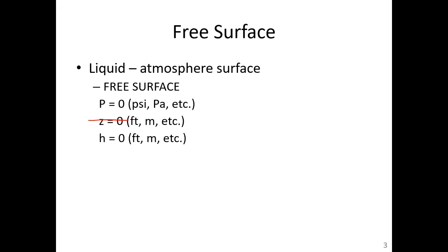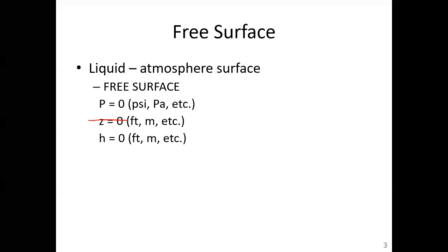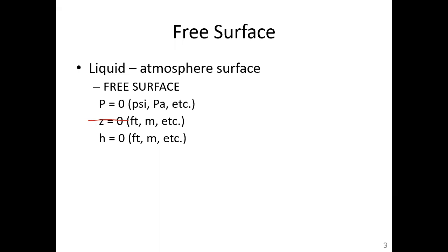When your atmospheric pressure is non-zero, you're typically using the absolute pressure measurement data. And you can certainly do problems in one or the other, but you can't mix and match. To get from an absolute pressure to a gauge pressure, we have to subtract off atmospheric pressure.